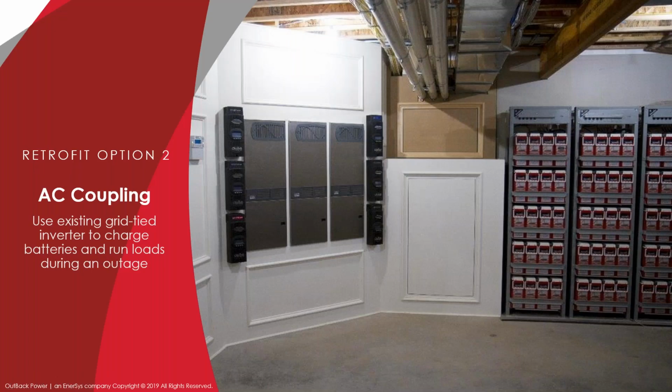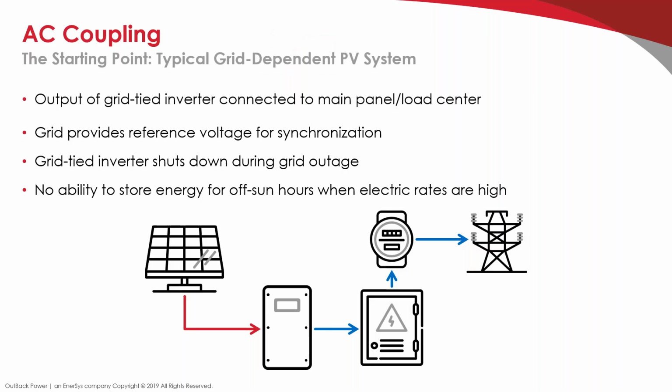Option 2 is AC coupling. Just to review, a standard grid tie inverter system, or grid dependent system, is just going to have the array sized up, and the inverter sized up to whatever the array is. That's going to invert into AC. It's going to get self-consumed at the main service panel. Anything that's extra is exported if you have a net metering agreement. So the problem is when the grid goes out, this system can't operate. Even if there's sun out there, it can't operate because it needs to have the grid to connect to and synchronize to.